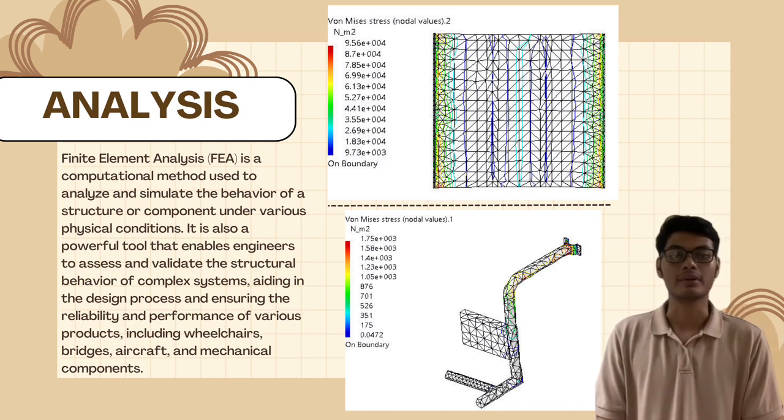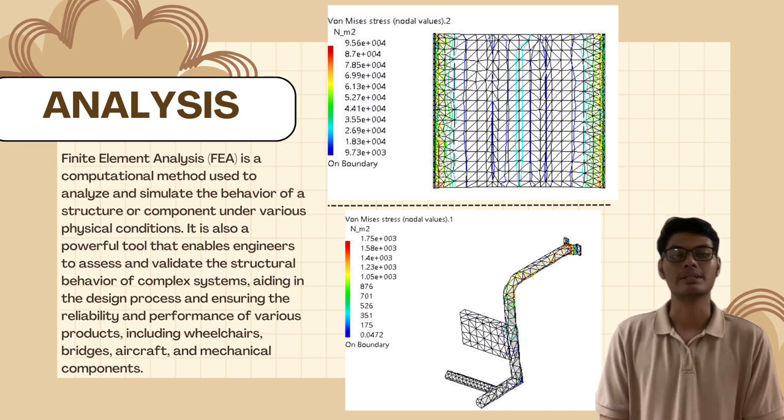Next, the leg part. Both sides of the leg part will use the same material, dimension, and shape. The material that has been chosen for this part is titanium. Then, boundary conditions are clamped at the end of the part, and the distributed load given is 300 Newton. According to the result of the analysis, it shows that element quality for the criterion stretch is 100% in good condition, while for the aspect ratio, 100% is in good condition and 0% is in poor condition.